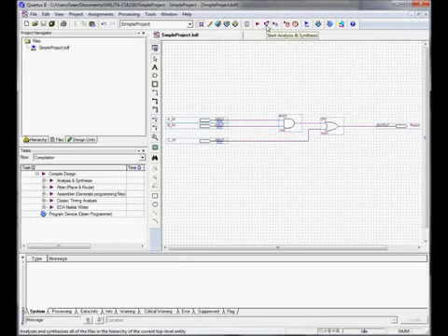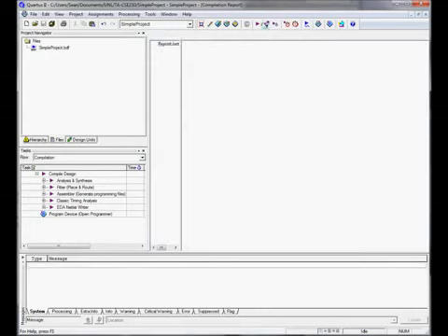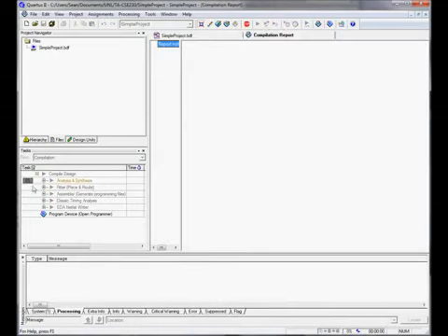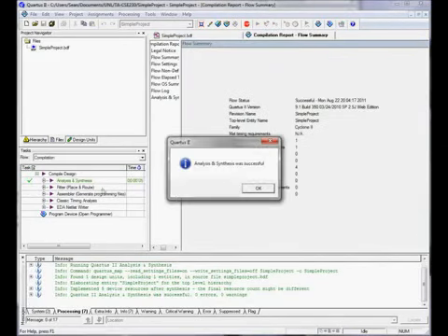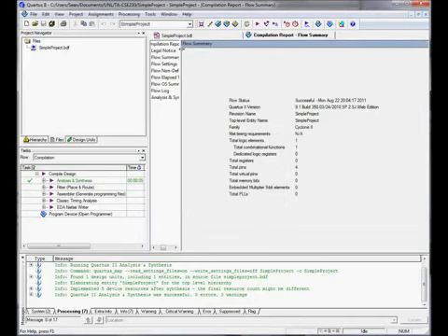We're just going to do the analysis and synthesis, which goes through all the compilation, but none of the necessary fitting and plotting for the chip specific. So we're just going to click that. You'll start to see over here, there's a percentage bar that goes through each one of the steps, and hey, I didn't mess up, so that's a step in the right direction.